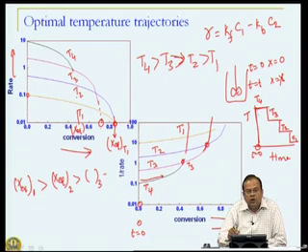So, what is the idea now? Initially we are nowhere near equilibrium. So, high temperature gives the advantage of kinetics and we are still not restricted by thermodynamics. But if you keep this temperature high for a long time, equilibrium conditions will be achieved and the equilibrium conversion at high temperature is low. So, you shift to a lower temperature T3 and keep doing this, so that you get the best of both kinetics as well as thermodynamics.